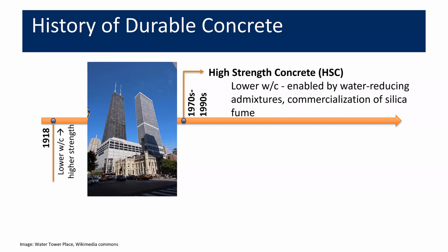However, pretty quickly after some laboratory work looking at the combination of the low water cement ratio and silica fume, there was a recognition that, hey, maybe that wasn't as good as it might seem, because there was a greater risk of cracking, which ultimately would compromise the durability of the structure.